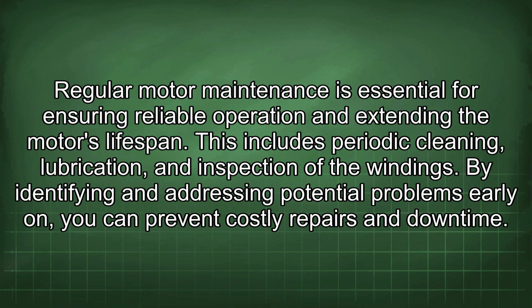Regular motor maintenance is essential for ensuring reliable operation and extending the motor's lifespan. This includes periodic cleaning, lubrication, and inspection of the windings. By identifying and addressing potential problems early on, you can prevent costly repairs and downtime.